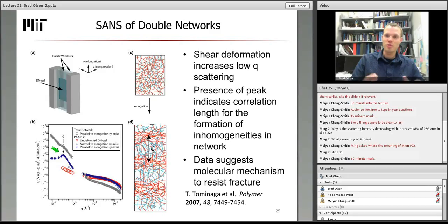And so if you recompress the gel, you would expect to see a relatively low modulus for compression. And in fact, this is what you see, that on recompression, the gels don't have the same strength they originally did on their first compression, because there can be some permanent chemical damage within the materials. But this really provides a fantastic way to get extremely high strength, high toughness hydrogels.